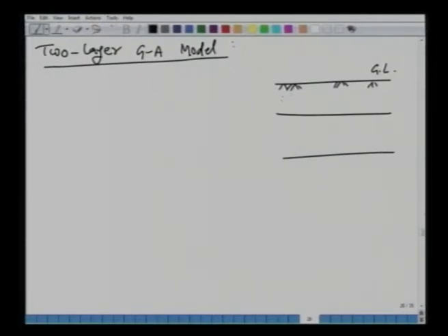The first one close to the ground is, let us say, some soil which has hydraulic conductivity K1, suction head psi 1, initial moisture content represented by delta theta 1, all right, and its depth or height is, let us say, h1. Okay. Below that we have another soil which has K2 as the hydraulic conductivity, a different soil suction head, and initial condition there may be different, okay, and its height is, let us say, h2.